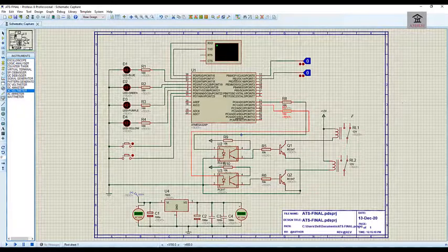So to do that, I am isolating this part of the circuit using light. So what happens is if I'm able to turn these LEDs inside these opto isolators on, this transistor will automatically turn on to drive the rest of the process. So I have this resistor here limiting the current into this LED here, and then I ground it. So it's just similar to what I have done here. So once there's a high on the input of these pins, the LEDs here will light on, and then this will in turn turn these transistors on to drive the next process which is involved over here.